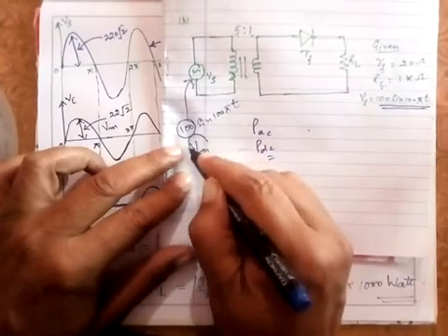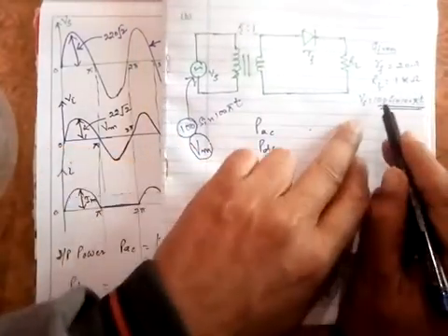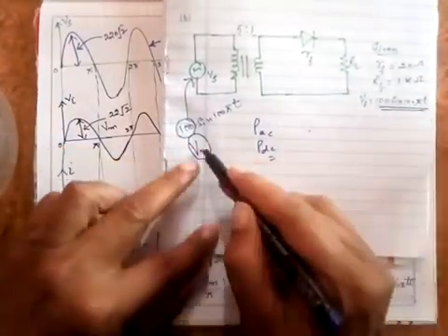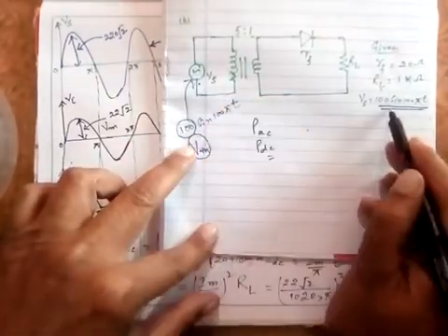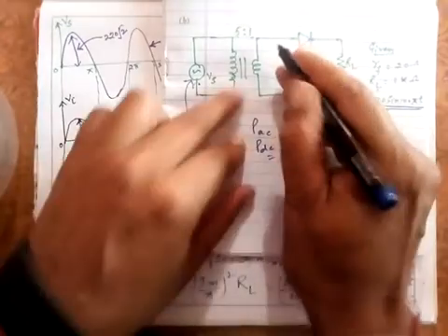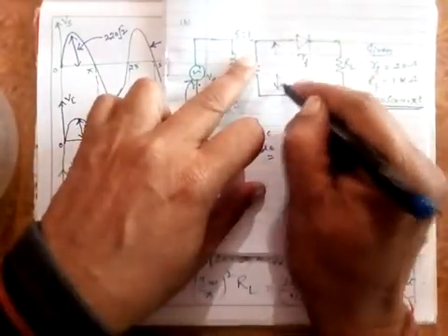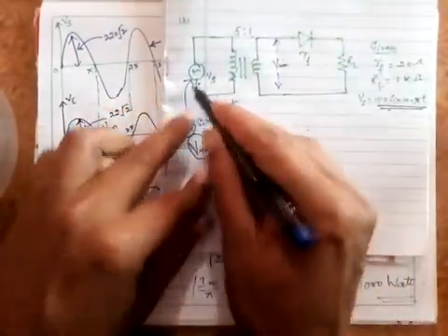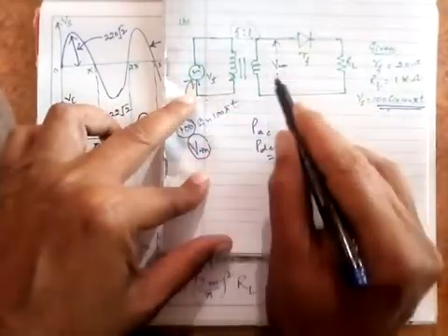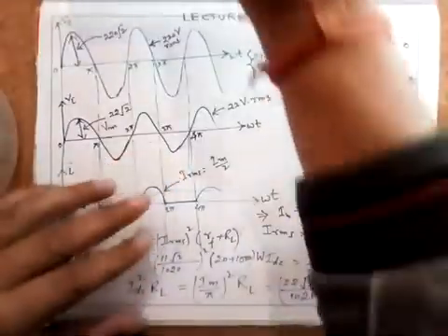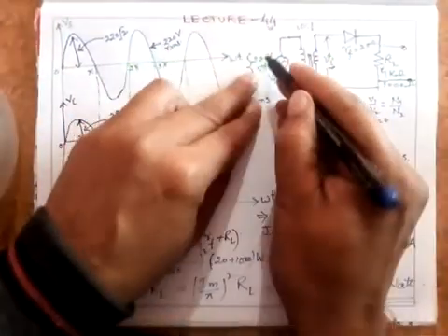It is not the RMS value. What I have applied here is, you say that either it is a sinusoidal signal of 100 volt peak value, or you say it is equal to this much. So whatever I obtain here, after this voltage is stepped down by this transformer, will directly be the Vm. But on the other hand, in this problem, this was the RMS value.